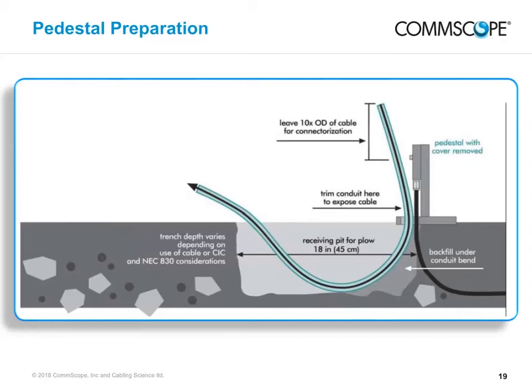If you are using CIC, keep the end capped until you've initially placed the cable. Use a ratchet shear to trim off the excess conduit. Fill the cable end with a watertight sealing foam. If trenching, unreel your cable or conduit as shown earlier. The only difference is that you will not need a receiving pit as you will already have the trench dug.